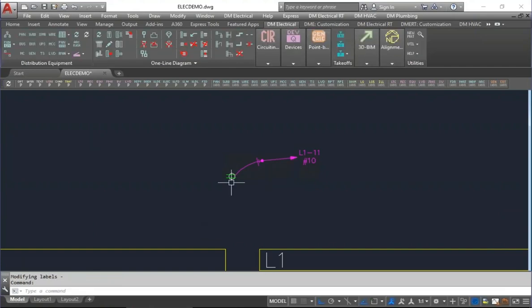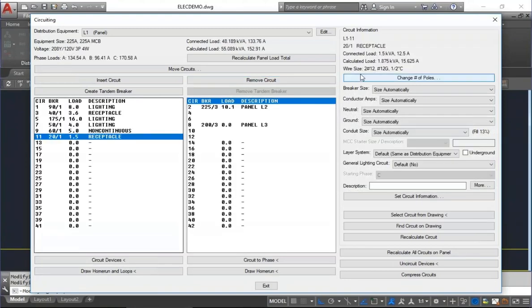It does kind of have to go through the database and make some changes. But we pull up this circuit, and now it's two number 12 ground, 1/2-inch conduit, rather than starting with 1/2-inch conduit at the beginning. No real difference in anything that's happening other than the output, because different people have different preferences on how they like to label their feeders and branch circuit sizes.